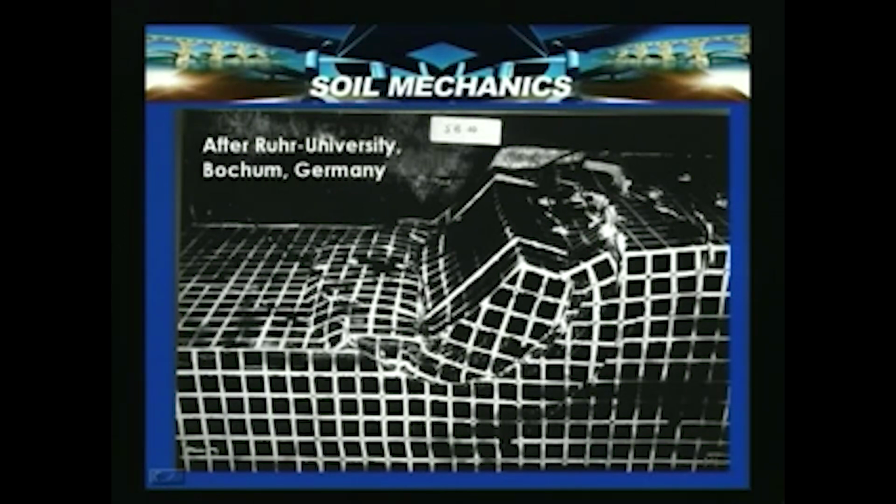You can see that this portion here is subjected to heaving. The stretch or extent of these failures can be felt up to structures up to this particular portion here. So, this is a physical model which is shown at the end of the test. This is the initial cross section of the slope, and after failure it is at this particular point, and these are the marker grids which enable us to identify the failure surfaces.